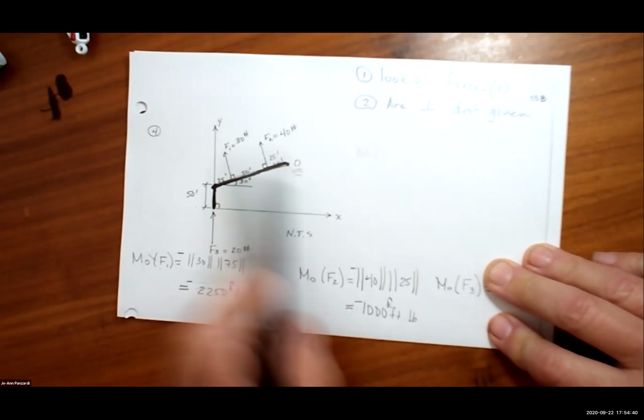So what I always do in these problems, until I got really good at it, is I put a marker along the whole line of action of my force. And then I look at the point and I see it more clearly. Look at the green line and the green dot. You could see where the perpendicular distance is. It just takes practice. If this black line is 100 and this is 30 degrees, I know the component in this direction is going to be 100 cosine 30.